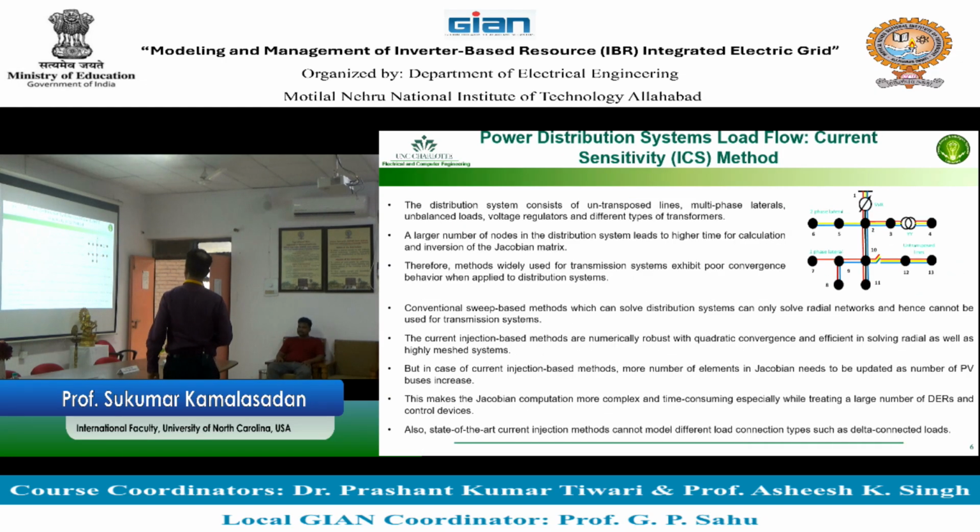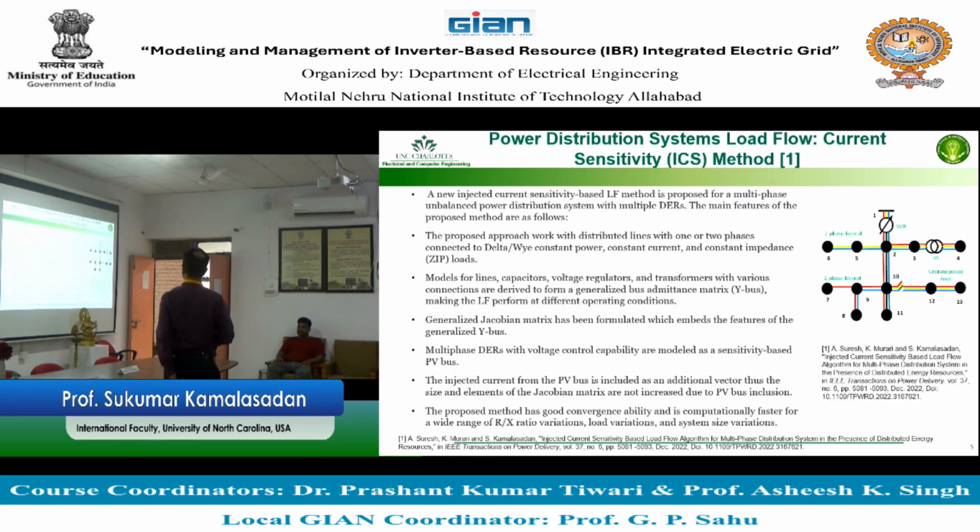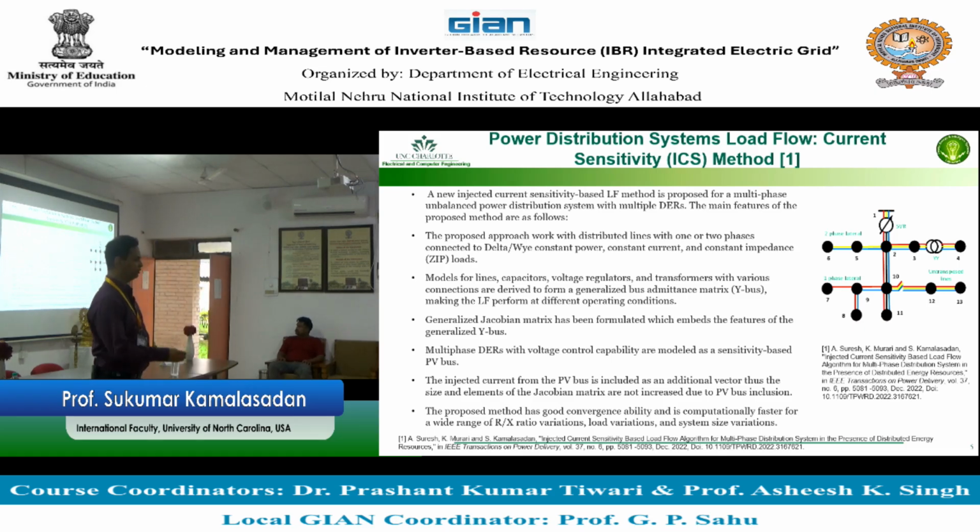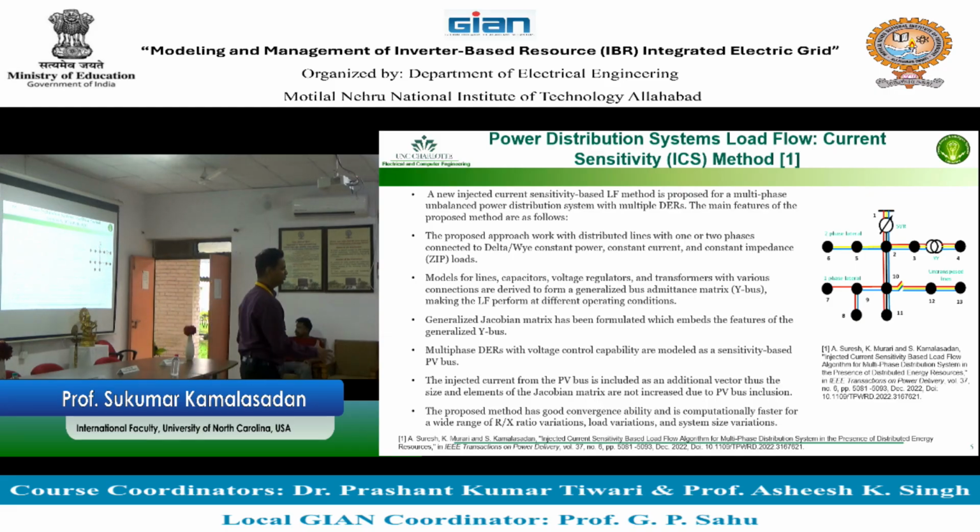For running the quasi steady state time series power flow, we looked at a power flow model which is different from forward backward sweep. Okay. So what we did was we looked at a model based on current injection or current sensitivity based model. We tried to introduce it yesterday. It was a little late in the game yesterday and everybody was tired. So I am going to reintroduce that for the first 5 or 10 minutes, which is the power flow model that you can run the electric grid.